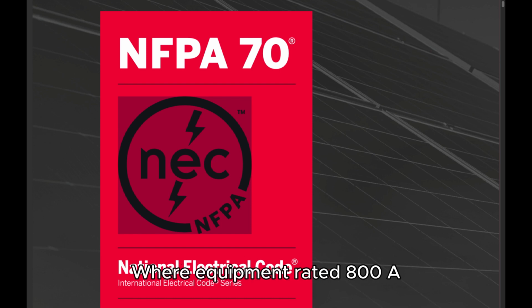Where equipment rated 800 A or more that contains overcurrent devices, switching devices, or control devices is installed, and there is a personnel door(s) intended for entrance to and egress from the working space less than 7.6 meters (25 feet) from the nearest edge of the working space, the door(s) shall open in the direction of egress and be equipped with listed panic hardware.